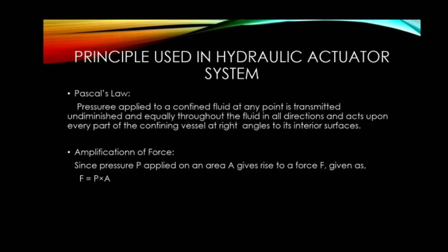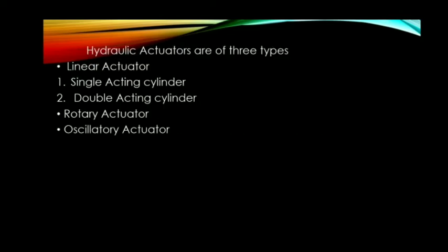Amplification of force: pressure P applied on an area A gives rise to a force F. Thus, if a force is applied over a small area to cause a pressure P in a confined fluid, the force generated on a larger area can be made many times larger than the applied force that created the pressure. This principle is used in various hydraulic devices such as the hydraulic press to generate very high forces.